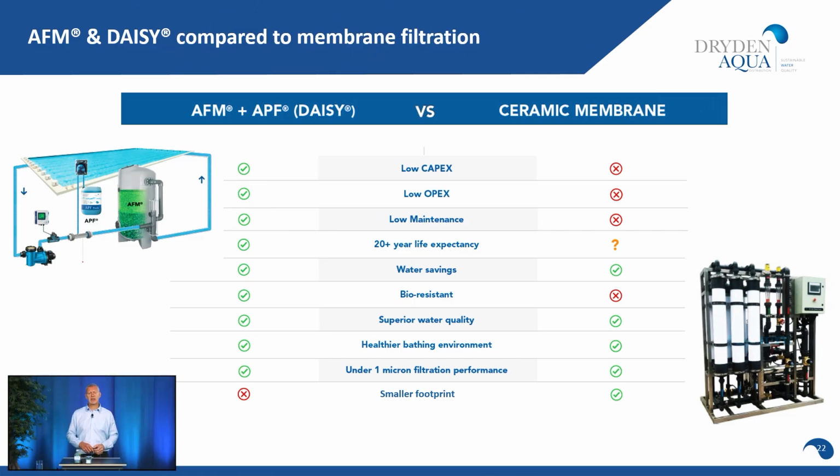AFM, as I've already mentioned, is 100% bioresistant. We can't say the same for ceramic membranes. They are subject to biofouling and do need to be cleaned on a regular basis with cleaning solutions. However, the water quality for both systems is very, very good. Healthier bathing environment, yeah, this is because we're not producing such toxic chlorine byproducts. We've given the ceramic membrane a tick there, but if the system were to become biofouled, then you would get an increase in such byproducts.